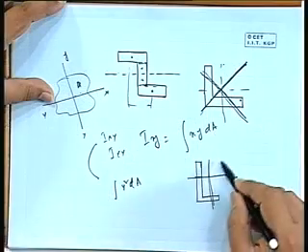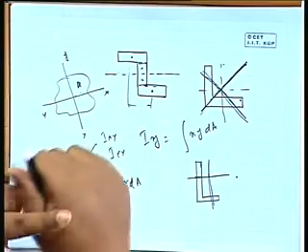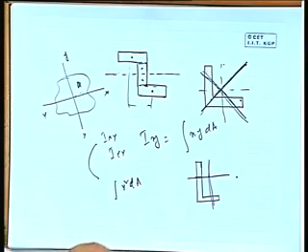It may be some direction, and perpendicular to that will be the principal direction. So any moment, if it is applied in the principal direction, there is no problem, we can straight away apply the elementary bending theory, My by I.